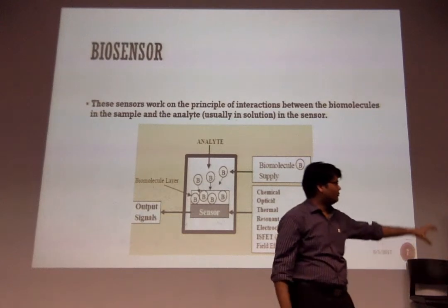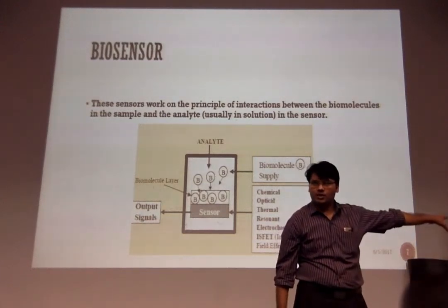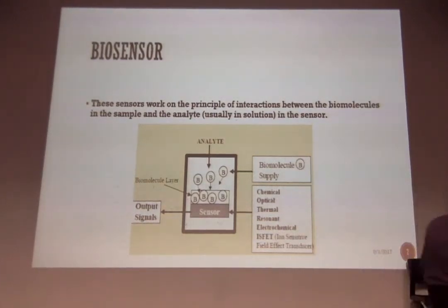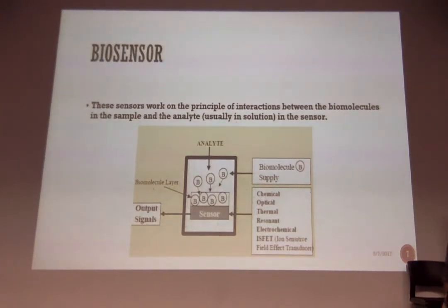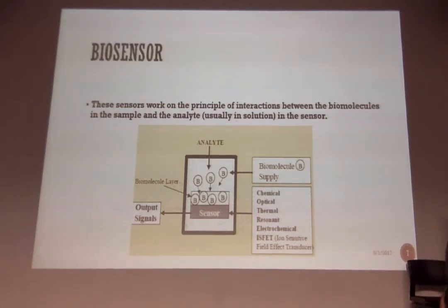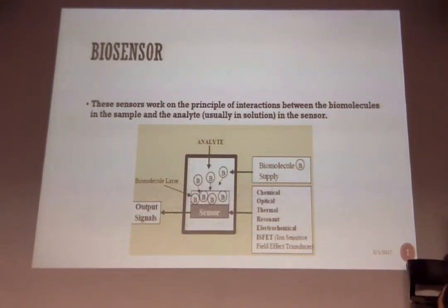So what do you make of this? If I connect a multimeter between these two and measure the resistance, what will the resistance be between these two points? Infinite. The impedance is so high, it's like two wires which are disconnected. Can you realize that? Yes, so this is on a PCB.